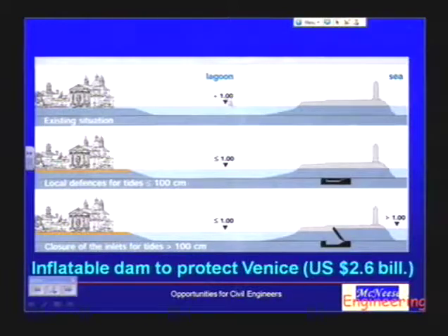So when the water is right around 1 meter, we're good to go. When it's less than 1 meter, we go ahead and let it drop. But when the water out in the ocean, out in this region, down the lower right-hand corner, gets bigger than 1 meter, then we actually have this little gate that pops up and keeps the water level inside.